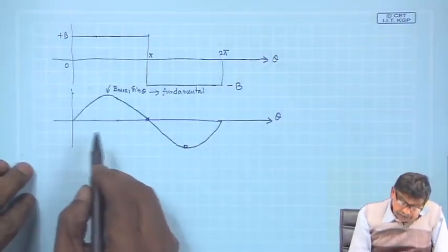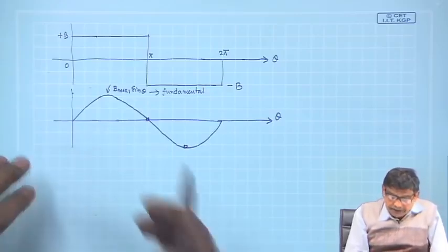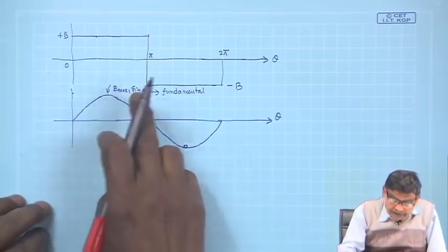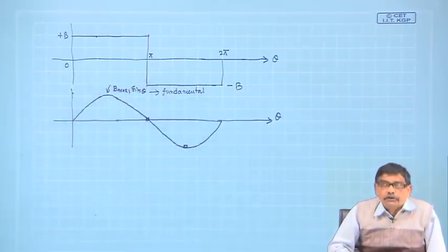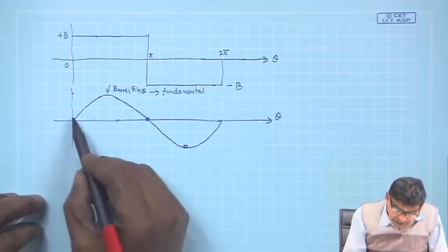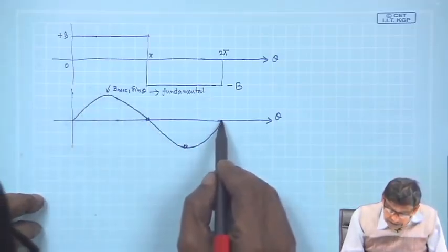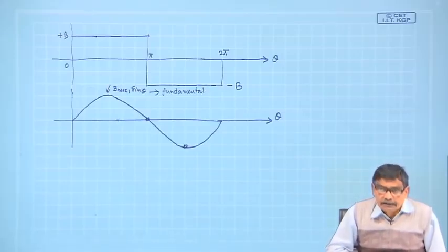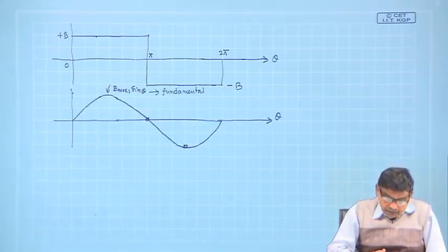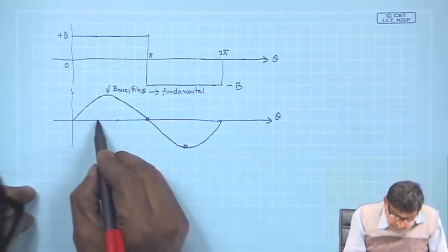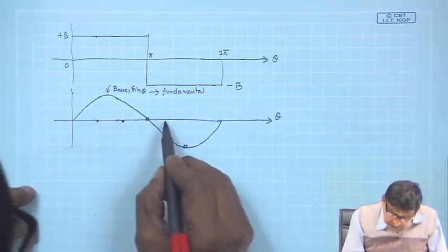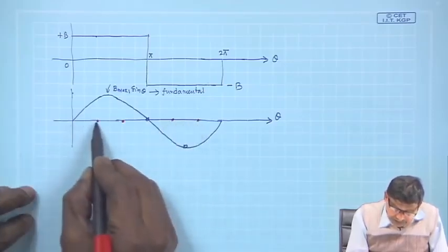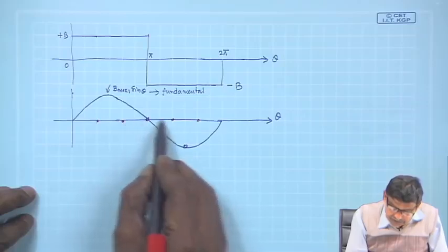Now, the third harmonic component. What is the third harmonic component? The third harmonic component, B max 3, will also be sinusoidally distributed, but when the fundamental makes one complete cycle, your third harmonic will make 3 complete cycles. That is why it is called third harmonic. So, let me divide these things with 60-degree intervals. Each one is 60 degrees, this red marking, this is 60, 60.